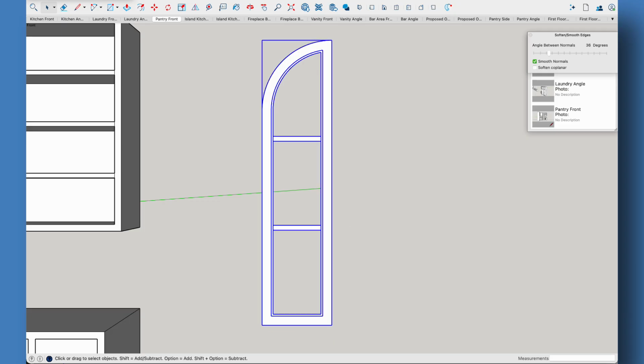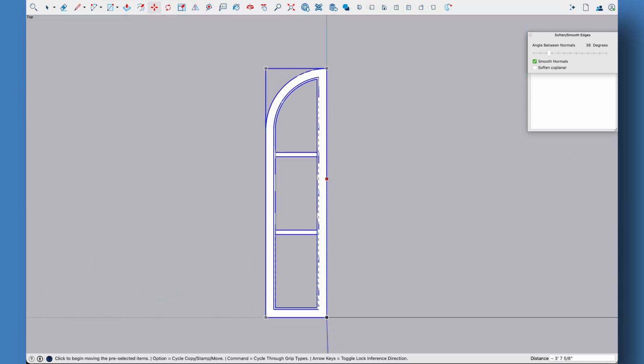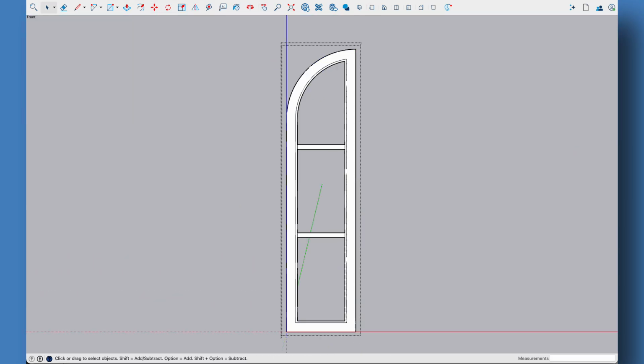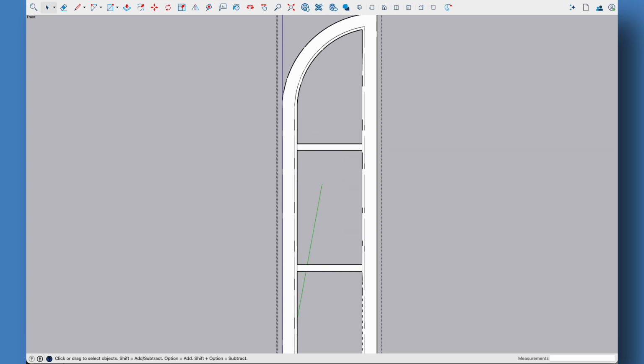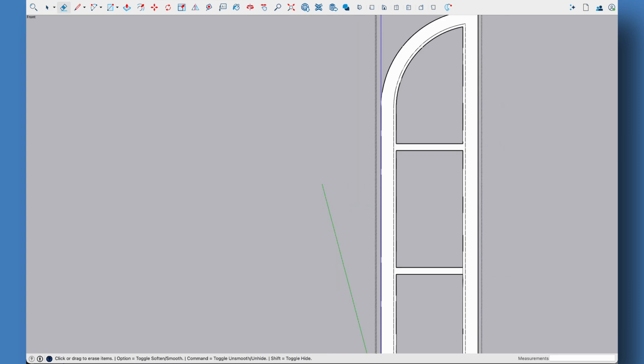Copy and paste it into a new SketchUp file, then flip it onto its face so it's laying flat. The homeowner wanted to see what the door would look like with 3 panes of glass instead of 4, so this is a quick and easy way to create that option. Before exporting, make sure to delete the lines inside each rectangle. If you leave them in, the mullions won't machine correctly. Save the file, then open VCarve.